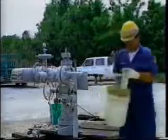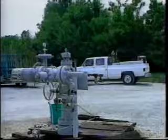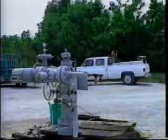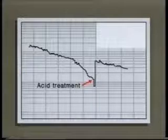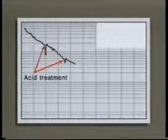The flowback after the treatment should be restricted, especially for sandstone wells. Excessive drawdown can result in the plugging of the formation by fines and precipitates. Sandstone reservoirs generally respond well to acid treatment. Sometimes, however, treatments yield poor results.